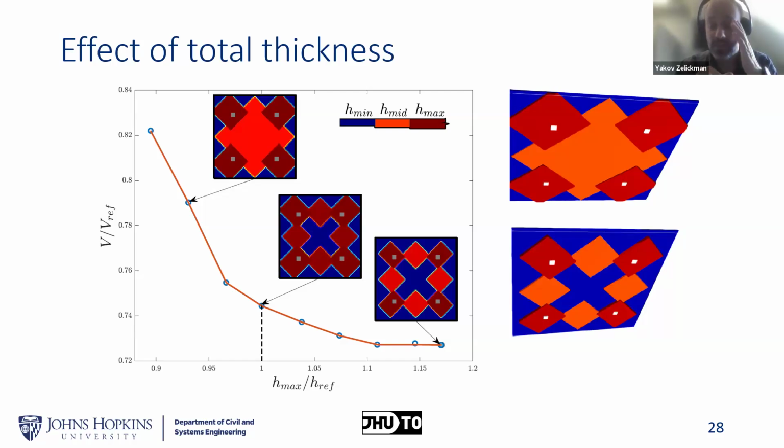In many cases, I will keep the thickness constant for all drop panels. In this case, I wanted to see the effect of different thicknesses, but generally, if you allow each drop panel to have a different thickness, you end up with very complicated designs and really kind of miss the point of keeping it simple.